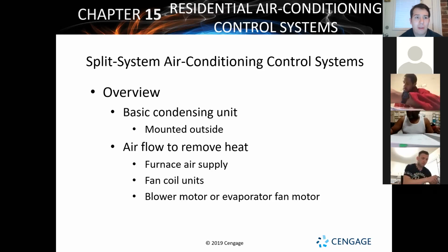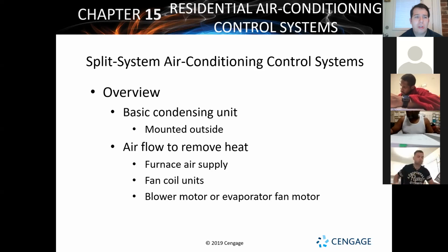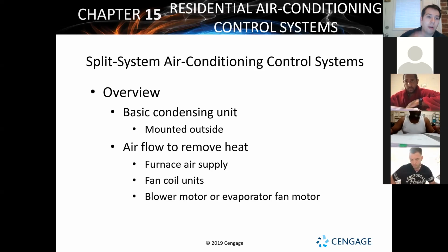I've had it where I went to a house, they had a brand spanking new air conditioner. Within 2 days, it failed. And the reason why, they hadn't changed their filters out. That was it. They just hadn't changed their filters out. And as soon as I removed the filters from the ductwork, the system started working perfectly fine within a matter of minutes. And I was just shocked at how quickly it made a difference, just increasing the airflow.